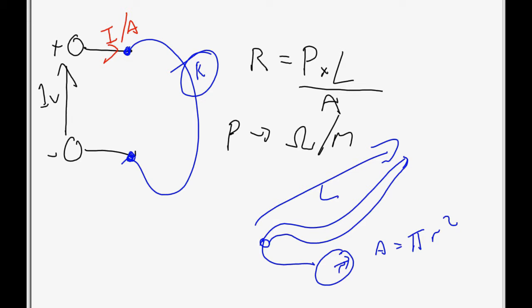Now, depending on what material we use, we can plug in our constant value for our resistivity. We can measure our length, and we can calculate our area by measuring the width of the cable. If we have the data sheet for the cable, it will have the size of the cable, usually the diameter or the radius, or its AWG or SWG size, which is all equated to various sizes.